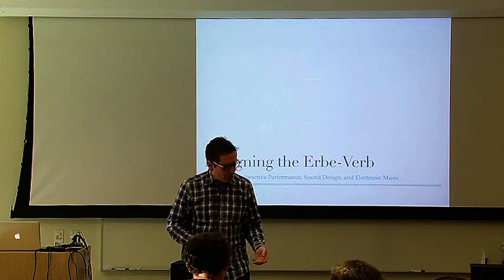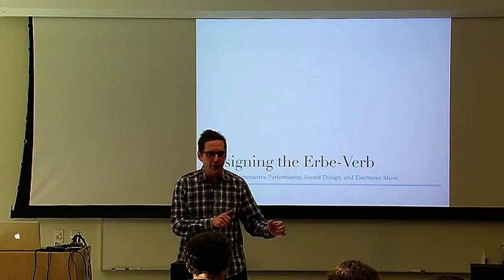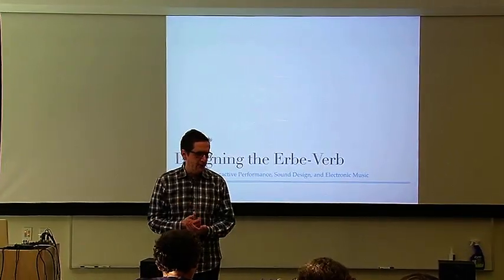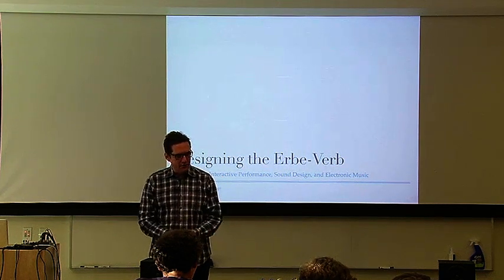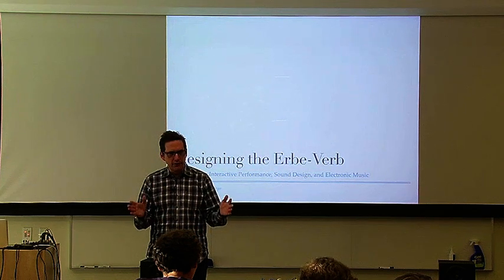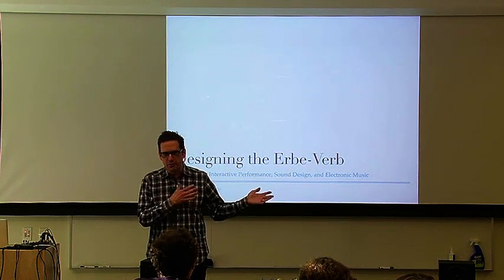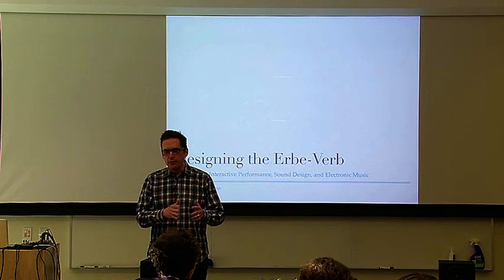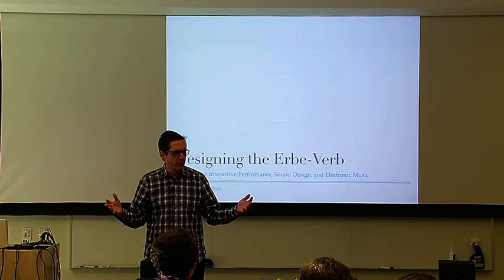For me, what I wanted is something that's a performance instrument where you have knobs, where you can change things, where people can find spaces that aren't essentially real. So I discarded the convolution approach and I started looking at the delay line approach. And there's a whole class of reverbs, and I'll be showing you the different ones, where you take a group of delay lines and you make things complex enough so that it acts almost like a real room.